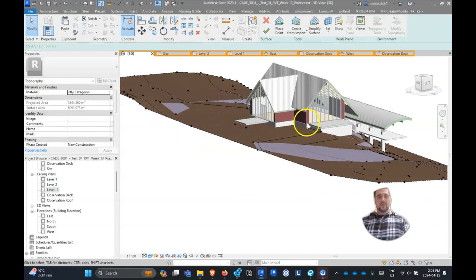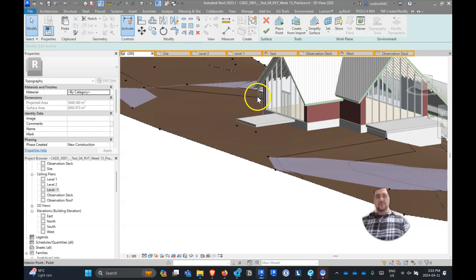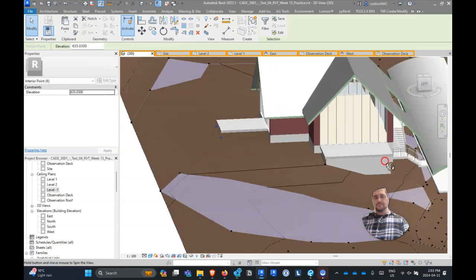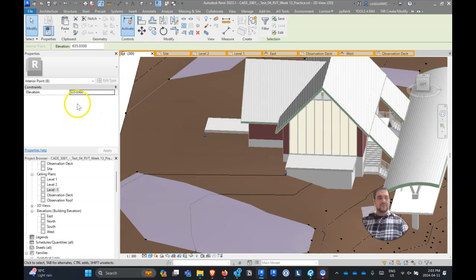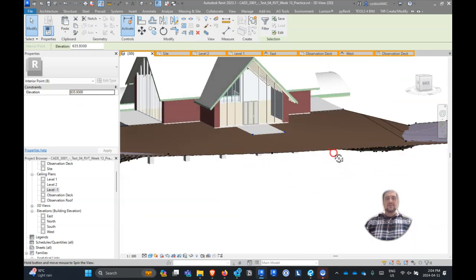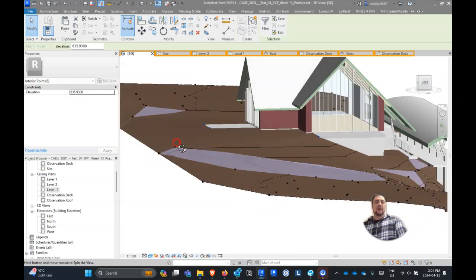What was our project base point? Let's go up. Let's see. Let's go up a little bit more. Maybe I think we'll go up to 236, maybe. See, okay, so we need to go down from that. 235. Oh, maybe it is 235.930. There we go. So now you can see just the slab barely sticks out of the ground now.